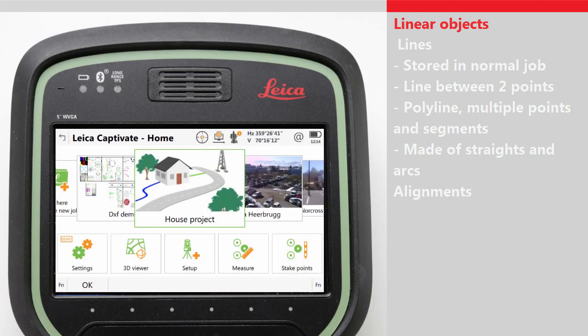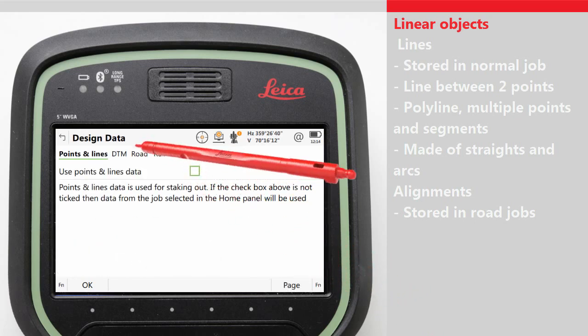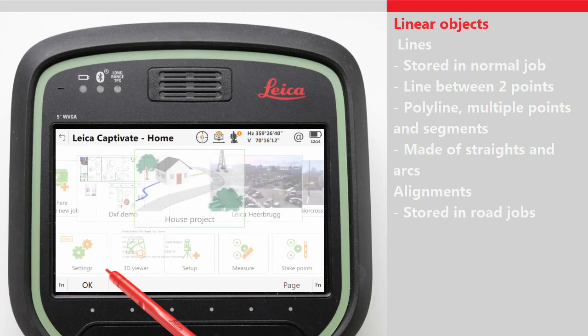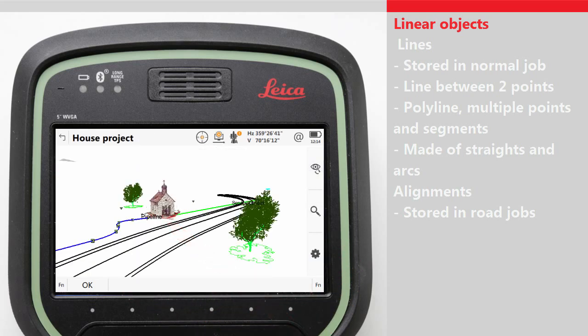A road alignment can only be stored in a road design job, and in order to see and use a road alignment, we need to turn on the use of the road job. In the home screen, choose Tap here to choose design data and select which road design to use. Another video will explain how to import alignments into a road job. When we return to the 3D Viewer app and view the same job as before, we can now additionally see the road alignment is shown.